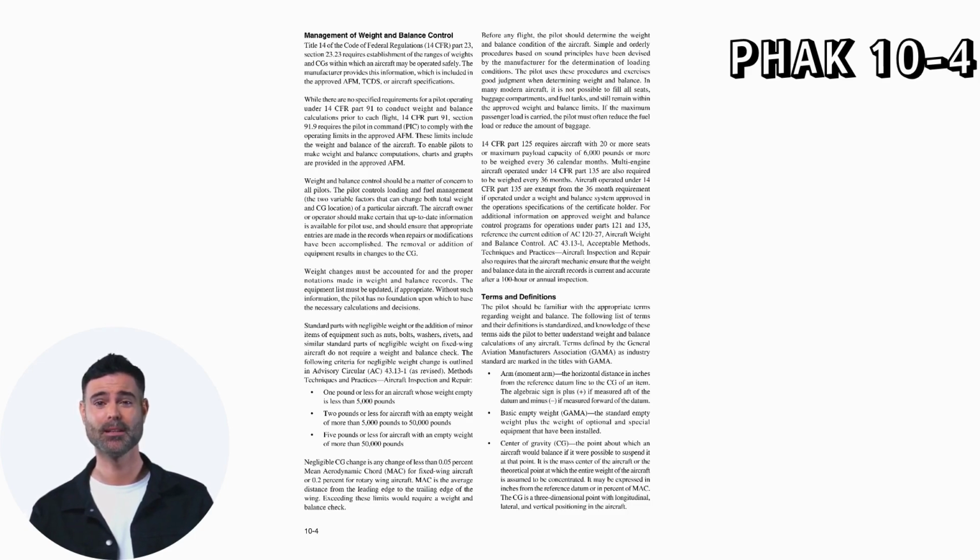Before any flight, the pilot should determine the weight and balance condition of the aircraft. Simple and orderly procedures based on sound principles have been devised by the manufacturer for the determination of loading conditions. The pilot uses these procedures and exercises good judgment when determining weight and balance. In many modern aircraft, it is not possible to fill all seats, baggage compartments, and fuel tanks and still remain within the approved weight and balance limits.